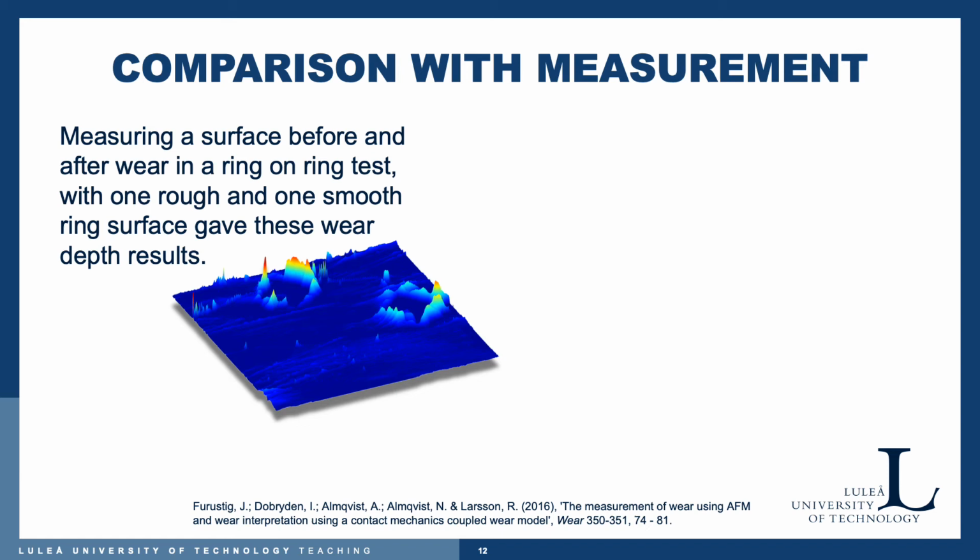It's because we have nano-indented these surfaces, not only to test the hardness of them, but also to be able to relocate the surface after wear to measure it at the same time, to actually quantify the wear like we have done here.